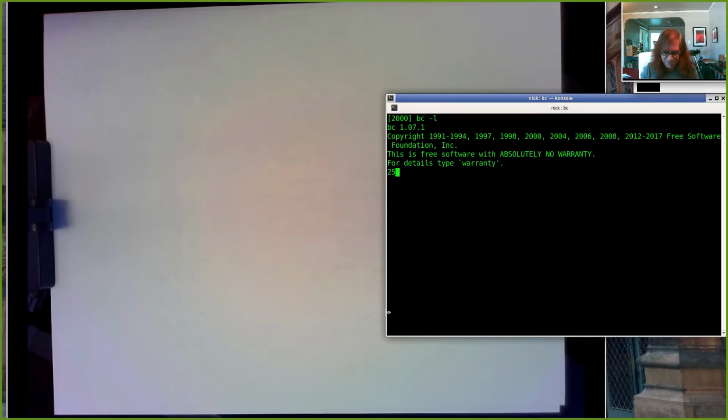Let's see. So 25,000. I'm going to guess that's probably 2 to the 15th, 32,768. So I think 15 bits would do it. Yeah, that's what I got. Okay, cool. And then for C, 50 over 0.015, so 4,096, 2 to the 12th. So 12 bits.